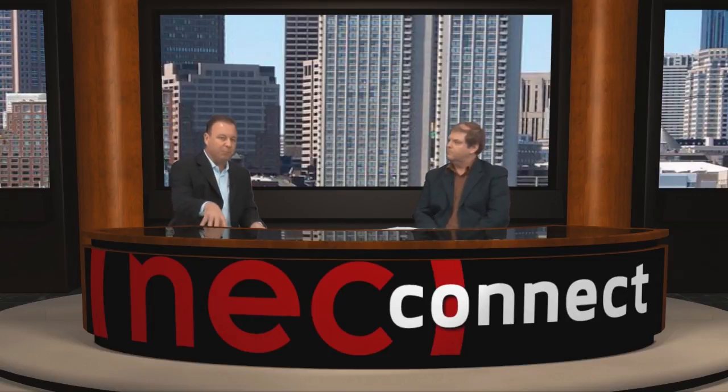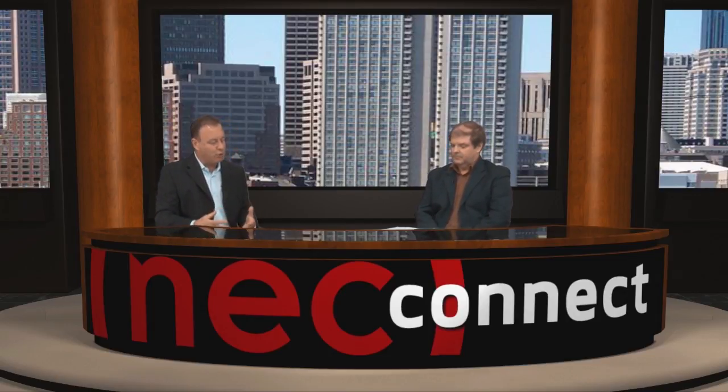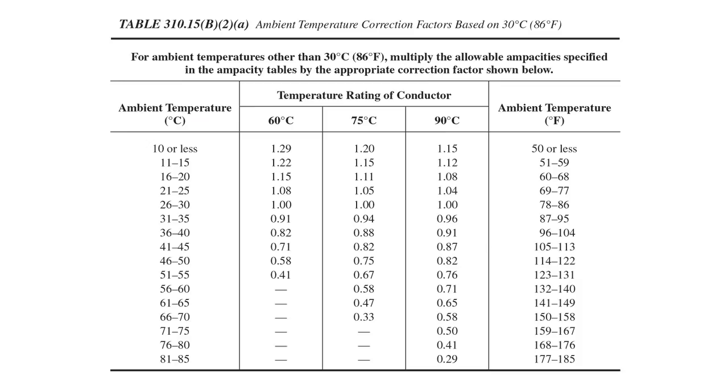The topic of this particular webisode, ampacity and why temperature is critical to understanding wiring methods and materials. Ambient temperature. What's ambient temperature? Ambient temperature is just the temperature of the medium that's around your conductor. It could be air, it could be insulation, it could be the earth. So it's whatever is around the conductor. And the table, again, as you look at some of these tables, they'll say buried in earth, in a raceway, or in free air. So you need to make sure you're using the right table. 310.15(B)(16) is for something that's in a raceway or in earth, that kind of thing. So it's not a free air ambient temperature.